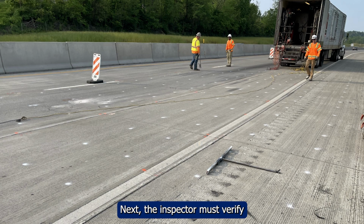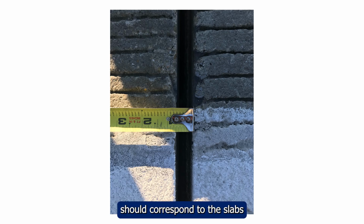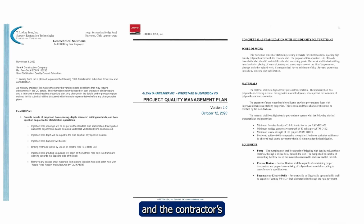Next, the inspector must verify that all injection hole locations have been properly marked on the pavement surface before any drilling operations begin. These markings should correspond to the slabs identified earlier for stabilization during the deflection testing or visual verification, and must follow the hole patterns shown in RC26M and the contractor's approved quality control plan.